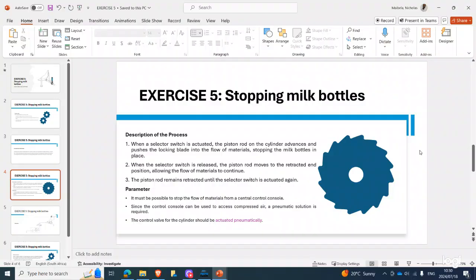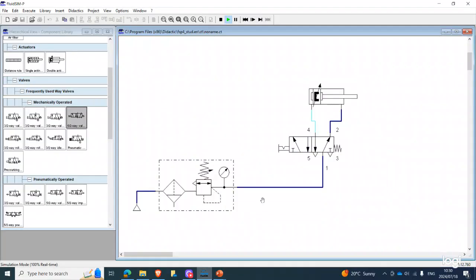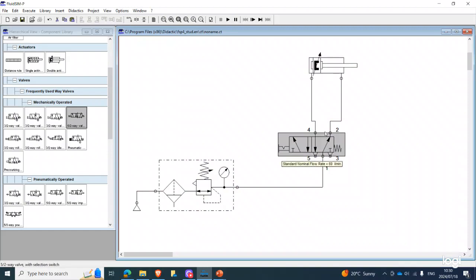So now, going back here, as I said in the previous exercise, a double acting cylinder is compatible with a 5/2 valve, as I mentioned before. So now you should know that a double acting cylinder is not compatible to be directly connected to a 3-way valve. For us to determine that intermediary component, it needs to be a 5-way.